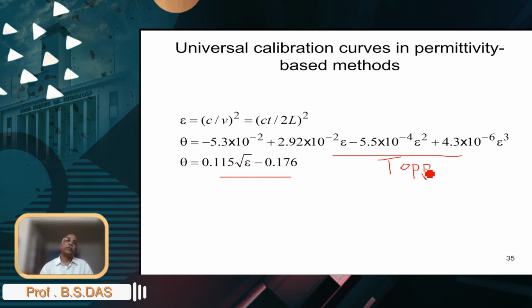And this velocity is basically the distance that the electromagnetic pulse travels inside the soil over time. Because it's a waveguide, you have a pulse going a certain distance, and as the waveguide ends, it comes back to the signal generator, so you have twice the length over time, and that's the velocity.